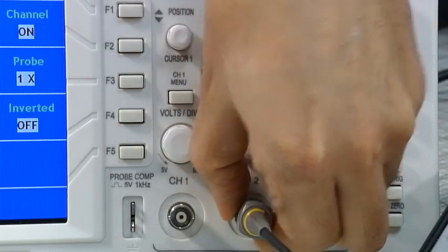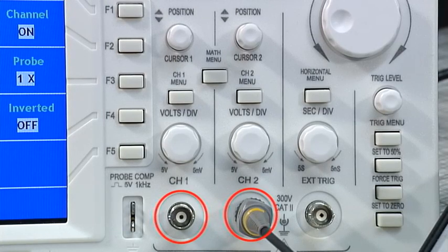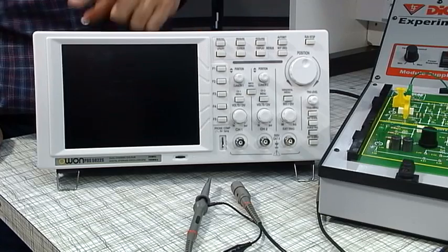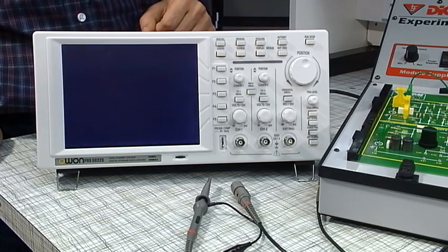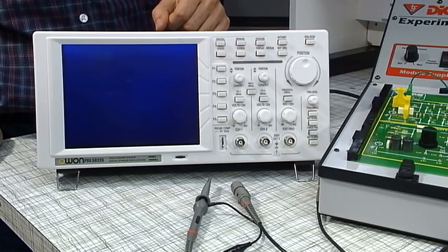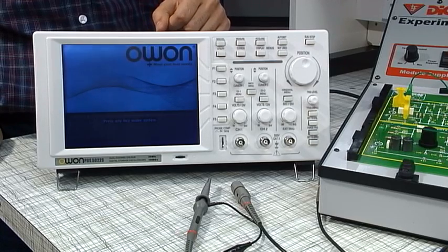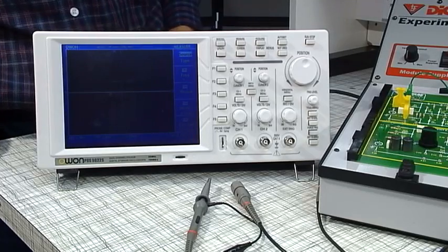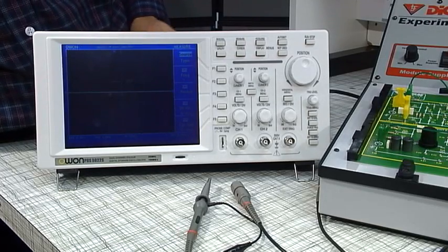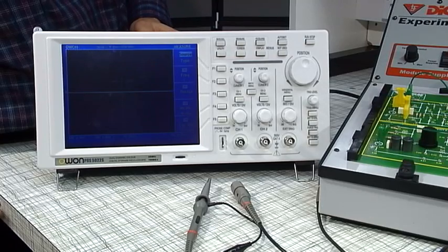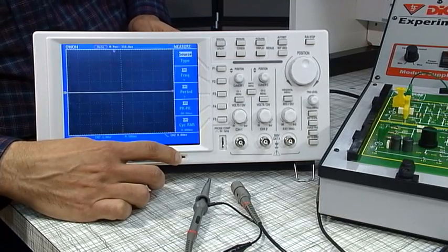The probe lead is connected to one of the BNC sockets on the front of the oscilloscope. Switch the oscilloscope on and wait for 5 to 6 seconds. Then press any key to enter the active mode. Adjust the screen intensity using the backlight dial so that the trace is sharp and clear to allow accurate readings